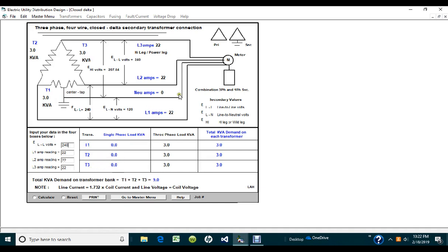And that's true, because what we did, we only told the customer where it'd be serving his 3-phase pump, which is what he gave us information on. So therefore, what it turns out to be is that the load on each transformer in this delta connection here turns out to be 3 kVA on each transformer, and it's all 3-phase load, because that's where we started off with here.